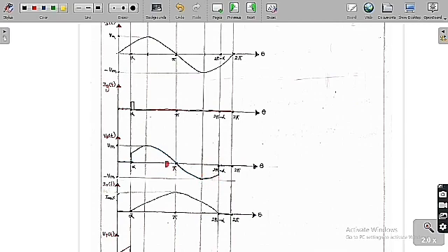So you can see clearly now, I have already told you the average voltage across the inductor will always be equal to 0, whereas the average current in a capacitor is always equal to 0. So here the average voltage across the inductor should always be 0. Because of that, if this is a positive area, here it should be a negative area. Both should be symmetrical, then only the overall area is equal to 0.